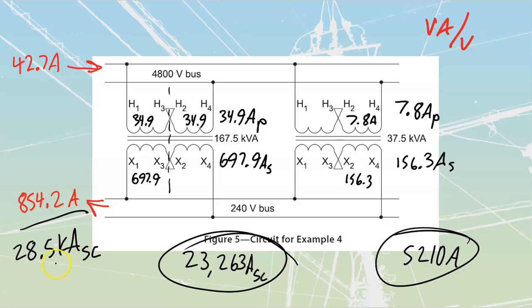And underneath the fault current, there's huge physical damage that happens. Bus bars themselves will literally pick up and curl like that. Huge ones, stuff that's the size of your forearm or maybe your leg or whatever, will go, and underneath the fault current, they will get bent at weird and unnatural angles just due to the magnetic stresses that are going to be on it. So even though some equipment doesn't have breakers inside of it, splitters and bus bars, they're still going to be rated for a certain number of kiloamps, because that's the amount of kiloamps of magnetic stresses that they're going to be able to withstand.